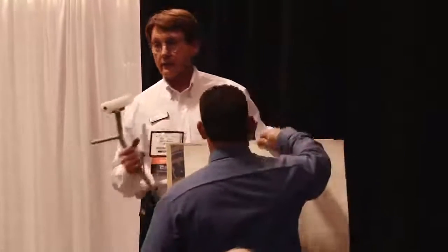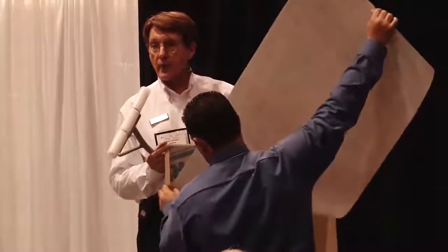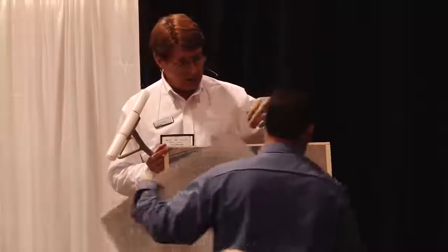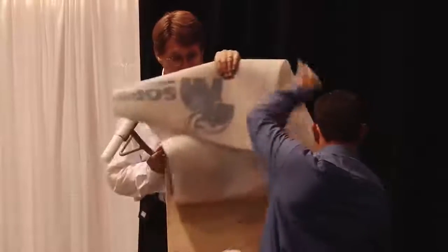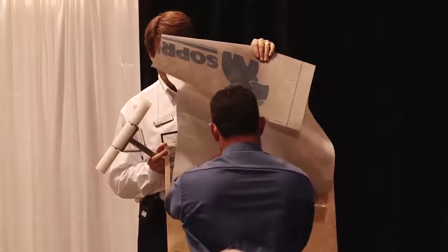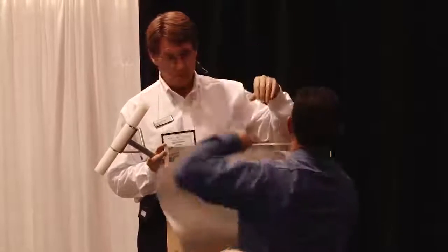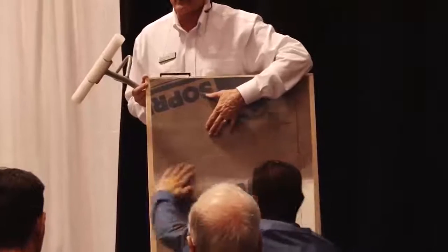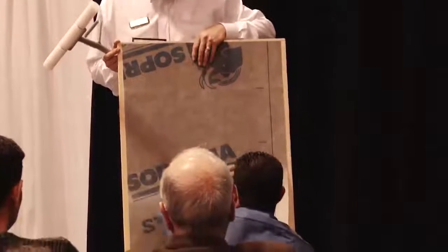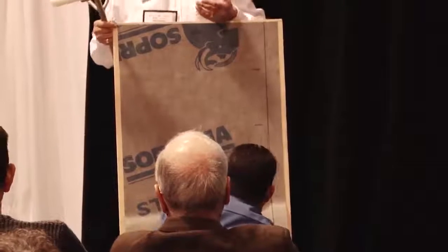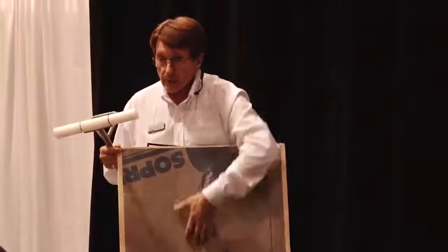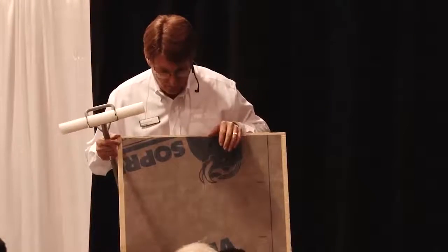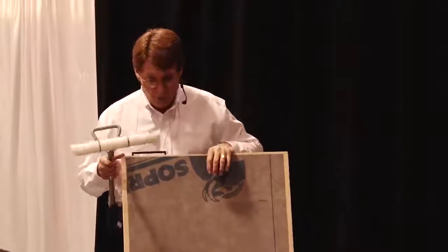So what John has already done is we've removed the top 4 inches of membrane so that we start to get our adhesion at the top. He can line the membrane up. You can lay the membrane out and then simply pull the release film from the underside. When installing air barrier membranes, it's always important that you basically start from the center, move your hands out in 2 directions to avoid those nasty wrinkles. You can see John is able to easily pull the membrane off.